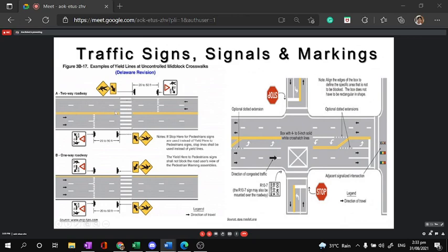Now, the line in the median, which is yellow or double yellow, only means a marking that you are not to cross to the other side of the lane, the opposing traffic. You cannot do counter flow, overtaking, or U-turn because it's regulated by the double yellow line. It's not allowed. Broken white lines mean there is a lane separation, so the outer lane and the inner lane are separated by this white broken line. Now the side white line on the roadside means that's the end of the travel lane, the section for vehicular traffic. Beyond that is already shoulder or pedestrian sidewalk.